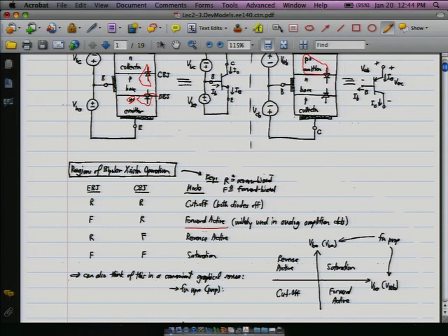It's kind of confusing because there's this mode over here called saturation, which if we were working with MOSFETs, saturation would be a great thing, because that's the operating region of a MOSFET. But it turns out that there's no relation whatsoever. It's just that whoever was making up the names wasn't making life very easy on anybody else.